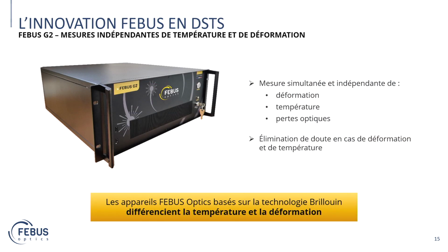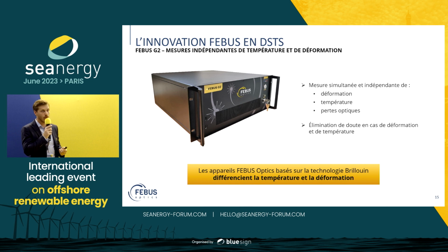Another thing that is quite interesting is when you want to use optical fiber to make temperature measurements, usually you're going to use Brillouin because it gives very good results and can go very far. But Brillouin as a whole is going to be sensitive to strain. You want to know, is it a thermal effect or a strain effect? If you use only Brillouin, it can be an issue.